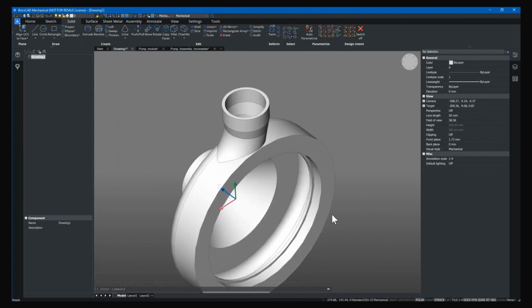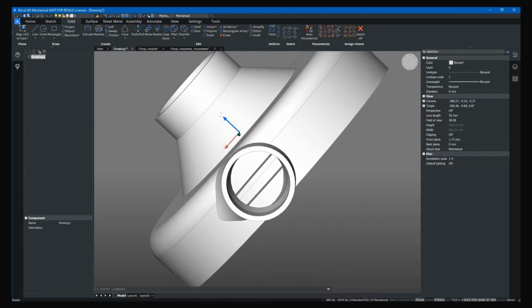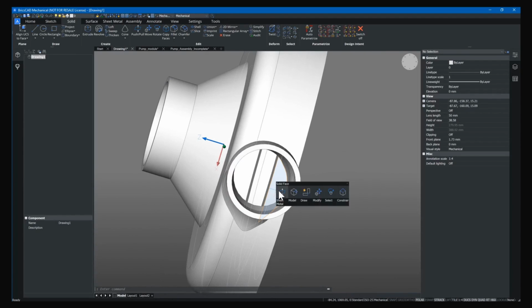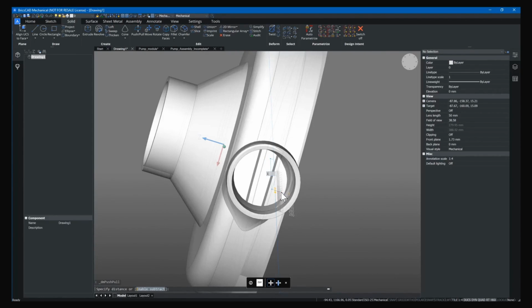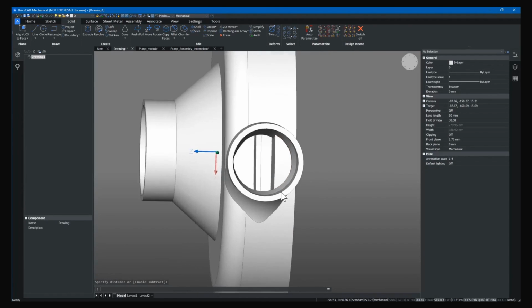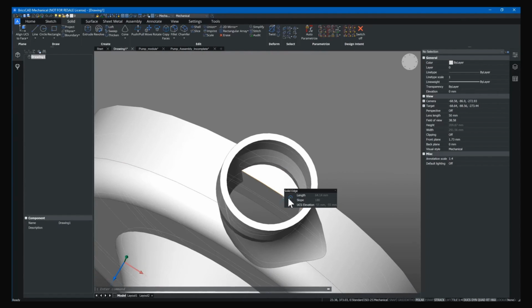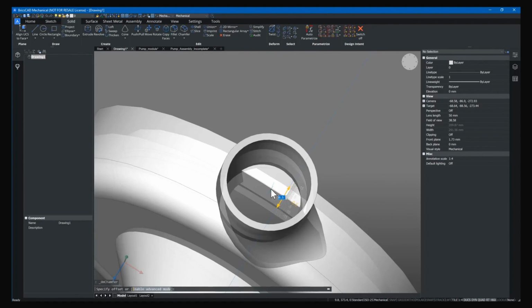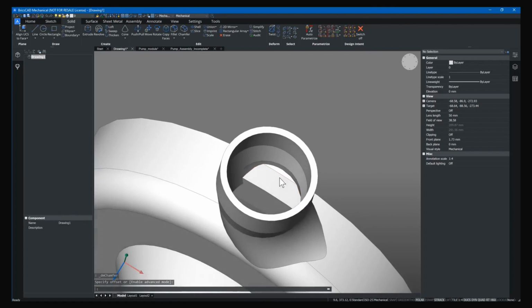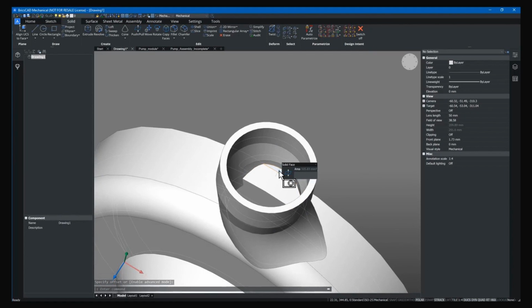On the top, we will see that there's a bit of a harsh connection here, so we can change the diameter here. We can now use this edge to add a chamfer to it, making a bit more of a seamless transition. Let's say 15 millimeters. This top face we can delete to make the chamfer complete, and on the remaining edge we can add a fillet.